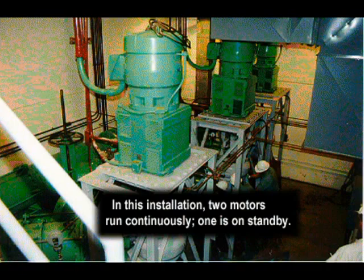Standby motors can be damaged by moisture. To reduce the problem, standby motors should be run at regular intervals to dry up any condensation which has accumulated in the motor.